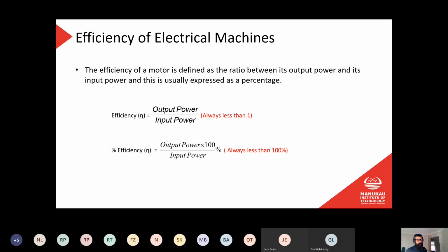So if one of those things costs you $30 and one of them is $2,000, you've got to ask yourself, well, is it more efficient because it cost me a lot to put this thing in? And in fact, if you do those sums, maybe we'll do one in class one time and have a look. But if you do those sums, you will often find that it might take several years for that heat pump to pay itself off. And then you've got to ask yourself, will I still be living in this house? How long is that heat pump going to last? When do I have to replace it again? If it takes me 5 years to pay for the heat pump in terms of the efficiency gains over using a regular heater, but the heat pump's only going to last 5 years, well, then I've gained nothing, because I've got to then replace it again and I have to start the equation all over.